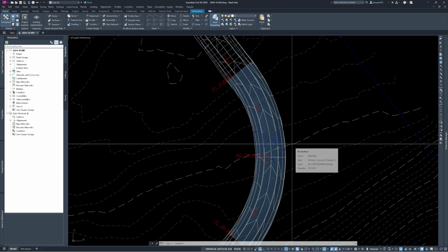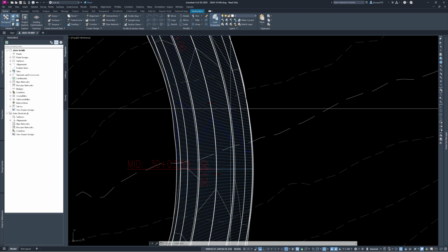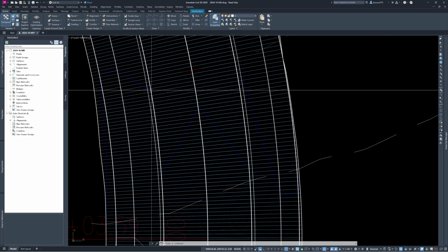So the 1275 comes off, creates our level area in this case for our sidewalk, and then it goes 2% down to the back of the curb, then to the face of the curb, and then whatever the slope of the road is at that point comes back up. It shows our crown of the road. This is 3% going perpendicular across here. And then it does the same thing on the other side and ties back off to that contour. So it's pretty slick when it works.